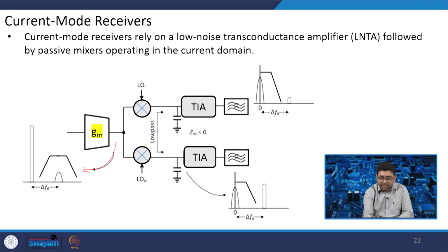If this is a TIA, which is a low pass filter in relation to this capacitor, this low pass filter will be up converted and looks like a band pass for both bands, meaning double side band. Here the low pass is at single side band, and at the RF input side it is a double side band, up converted to the LO frequency.